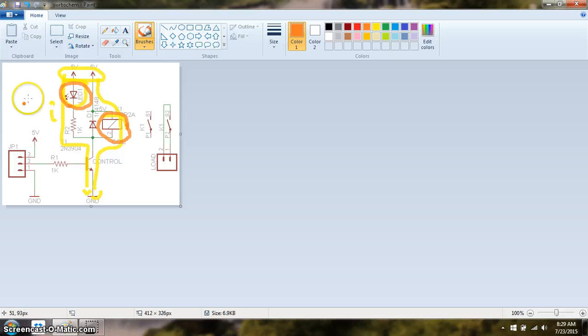Because imagine, let's say the relay is not working. Let's say this guy is not opening it. So you'll be thinking maybe the circuit is not getting the right voltage, or something is happening. Maybe this guy is not working. There could be so many possibilities. But if we have an LED as an indicator, we could right away say, no, it is getting the current. Things are fine. There is something wrong with probably this coil, or something wrong with this guy.